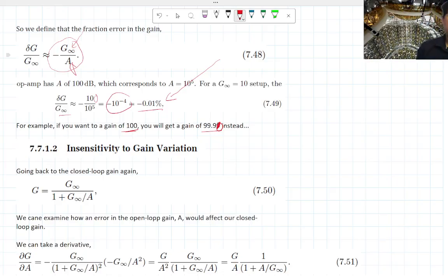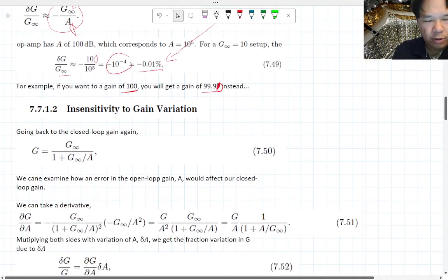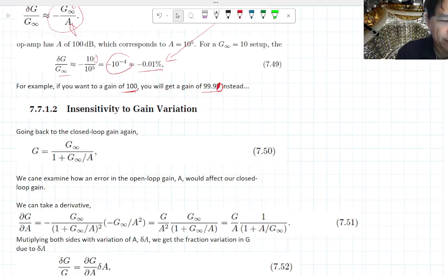That's why a lot of amplifiers tend to stay around 10x, and you'll see people building series of amplifiers like 10x, 10x, 10x. Why didn't you just build 1,000? Because you don't want the amplification to be too large, and we're going to see how this also affects real life, where there's propagation time, which causes things called slew rates and gain bandwidth.